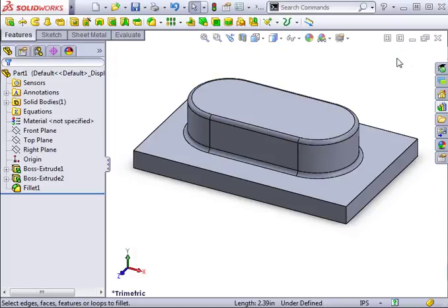Once the fillets are in place, you can get rid of the base feature if you wish. By doing so, you can simplify the forming tool and make it easier to identify when you use it later. Before I cut away the block, notice that it would be impossible to create this fillet without the use of the base. That's why it was created in the first place.